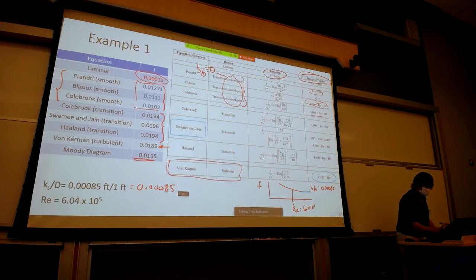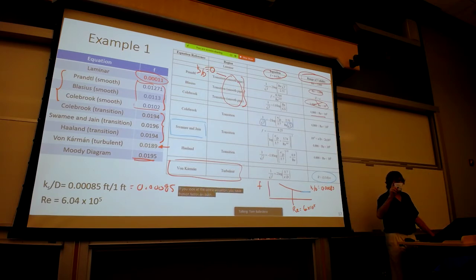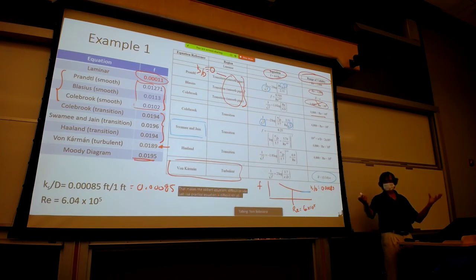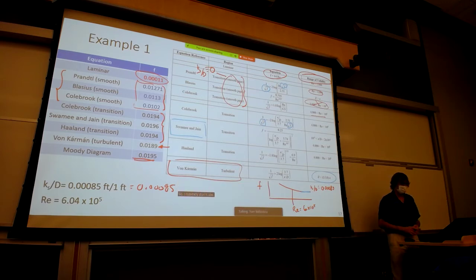If you look at the Colebrook equation, you have friction factor on both sides. In fact, you see f to the 1/2 over on the right-hand side, and that was one of the axes on the Moody diagram, the upper horizontal axis. That makes the Colebrook equation difficult to use, just like Prandtl's equation is difficult to use. When f is on the two sides of the equation, it's a trial and error solution. So I typically don't use either of those because I'm not a big fan of trial and error when another equation is going to give me a good answer.